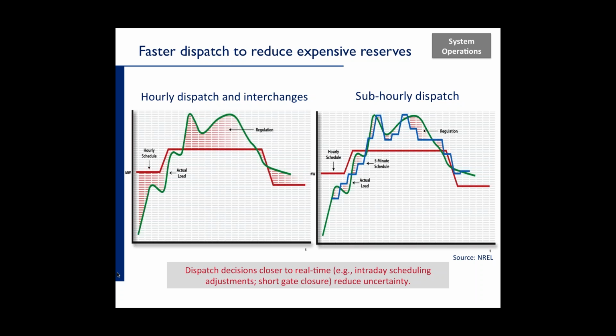And so in the economic dispatch, I'm allowing more units to respond. They're responding more quickly, and so I can incorporate all the response to variability, or most of the response, into a 5-minute economic dispatch, which really helps and brings out some flexibility that you have in the power system.